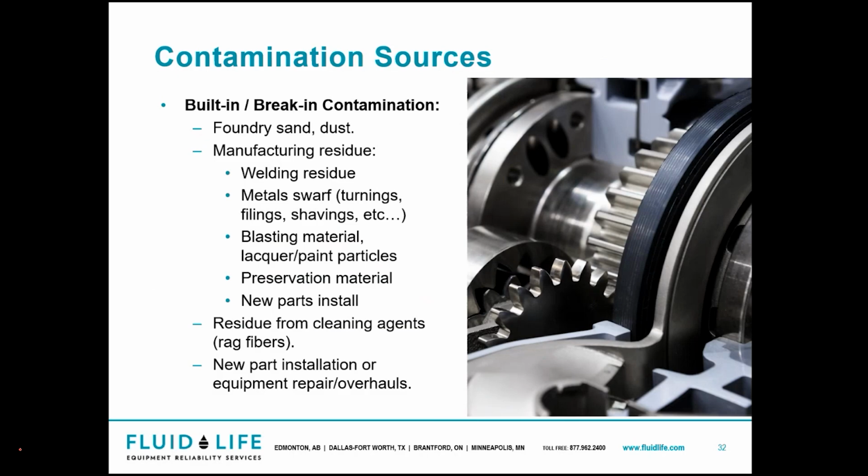And then built-in contamination, like I mentioned before: foundry sand, manufacturing residues, any sort of rag cleaning residues. That's why I suggest white towels or any sort of lint-free rag for cleaning, because those particles get in there. The real bad actors are where you buy those bags of ripped up t-shirts, or the boxes of ripped up pieces of old clothes that are used as rags. Terrible rags for cleaning.